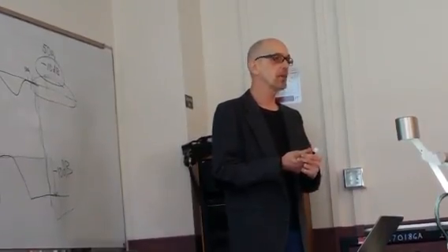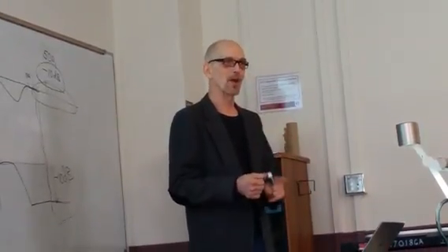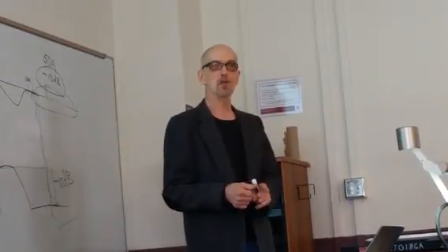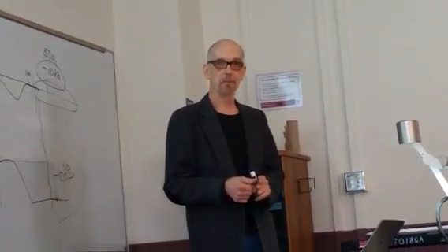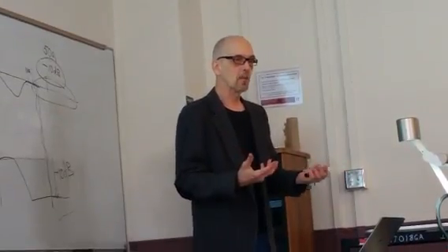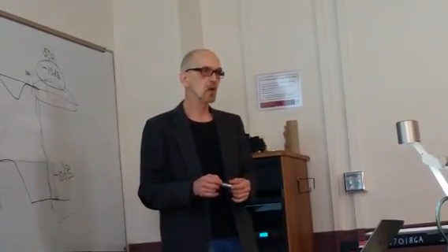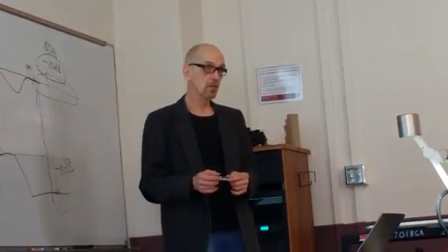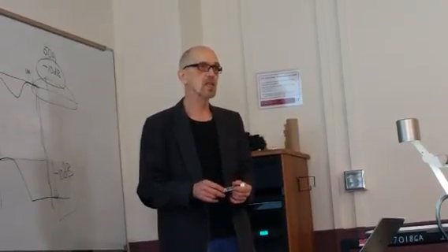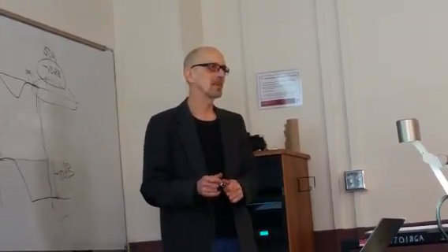So you simply compute that steady state error for a ramp. In this problem, it's not for a unit ramp. It's for the biggest slope ramp with gamma. But that's just a constant. The authors talk about these K sub V and K sub A, these steady state error constants. You're looking at K sub V because it's a velocity or type 1 system. But please, again, don't forget gamma in that thing.